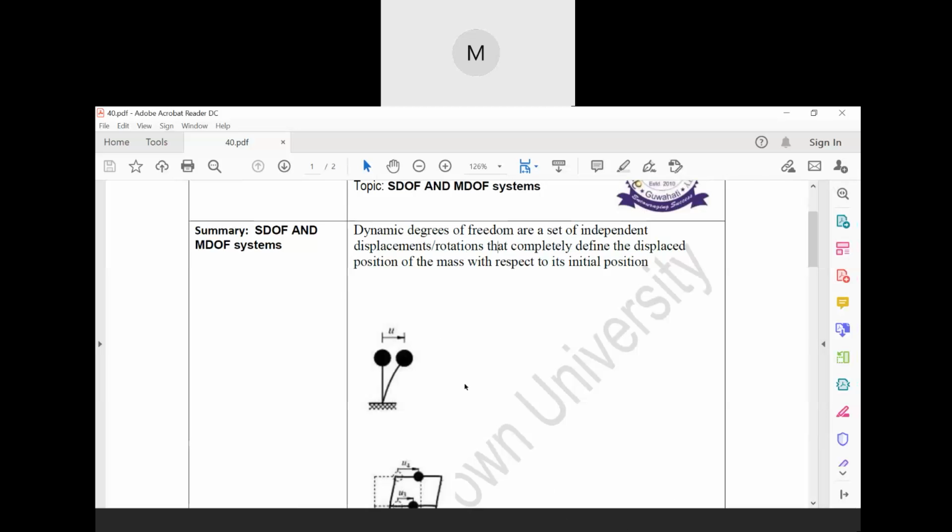this U thing is a lumped mass model. Okay. So here, this is a mass, and this is the base surface where it is fixed. Now if this surface is vibrated, then this surface is displaced by U. So if it is displaced by U, some amount of vibration is occurring. So that is a type of system.